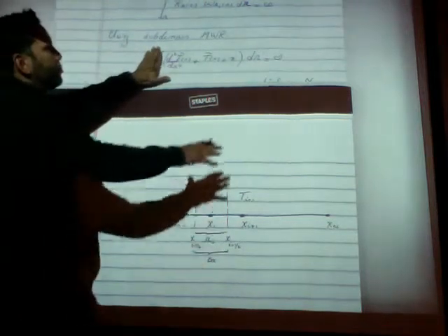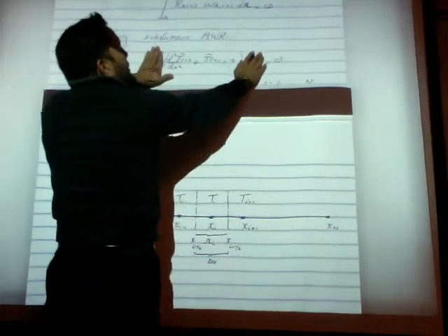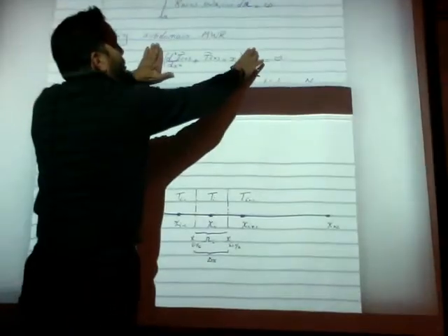Right now it's going to be slightly different because we still have to deal with the integral. The integral didn't disappear, which is usually a good thing for numerical techniques, that an integral stays. Because when you try to solve something in strong form, this is called strong form. An equation, a differential equation, is called the strong form of the conservation. You're basically doing a point-wise conservation of equilibrium, or maintenance of equilibrium, point-wise, when you do this, the strong form.